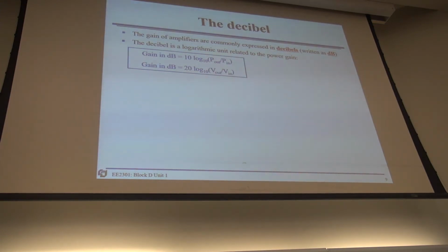So the power equals I times V, right? This is V squared divided by R, or the I squared times R. So this is so clear. But R is a constant, you don't change, right? So only those V is changing. So that's why we always have this type of a 20 log 10 type of thing.